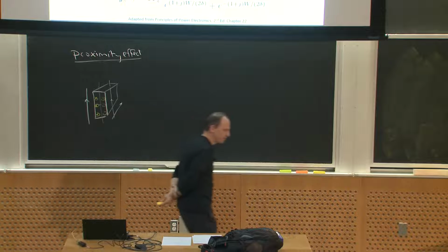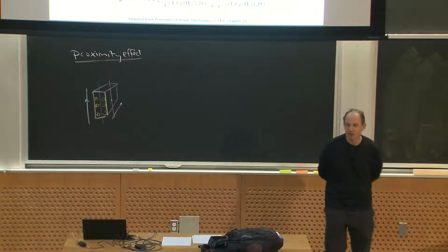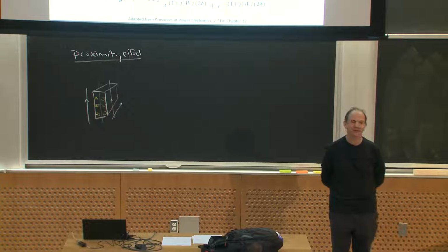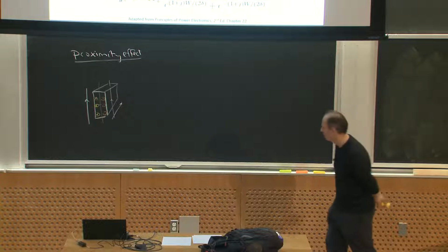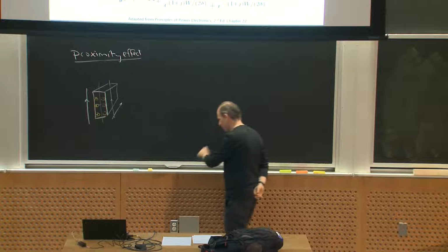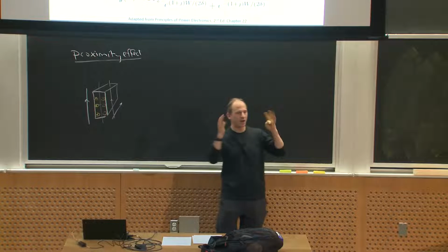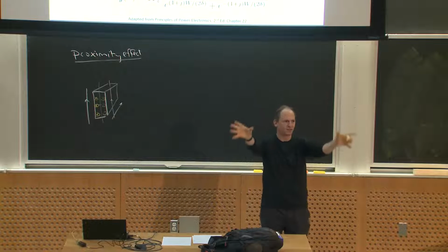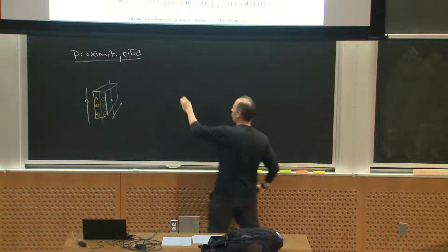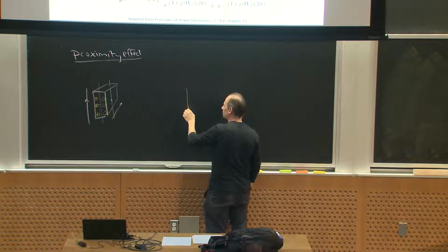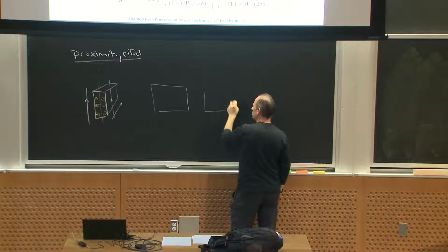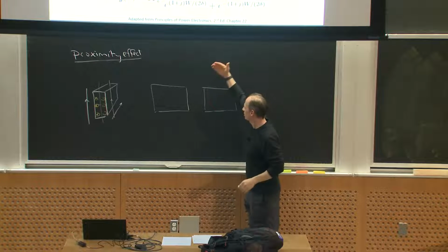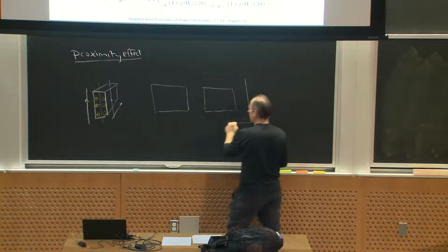Why is proximity effect particularly bad? Because I'm inducing loss in this conductor, even though I'm not getting to use that conductor to really carry any current. Why should I care about this proximity effect? Because imagine I have some core, like a pot core, with a center post, and then a window where I'm winding currents. Here is my core, a cross section of the core.